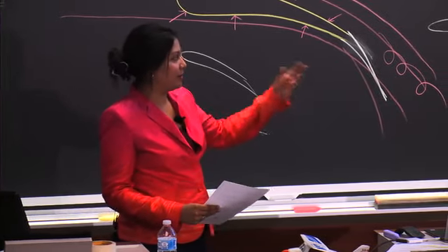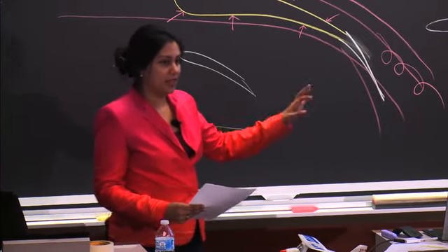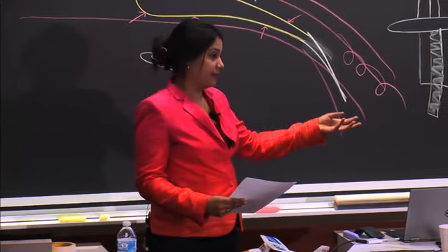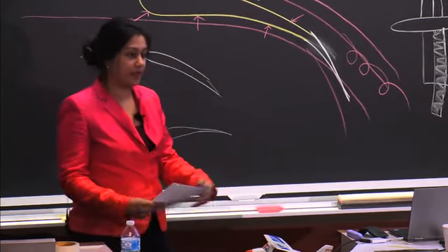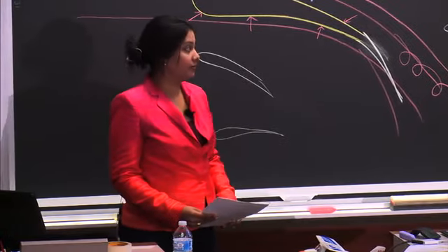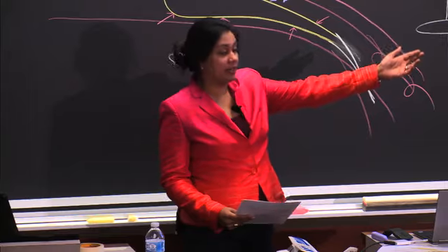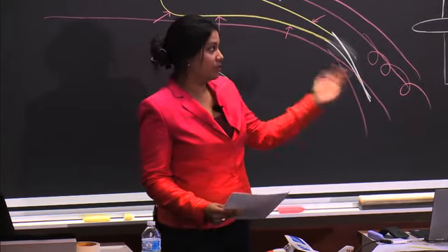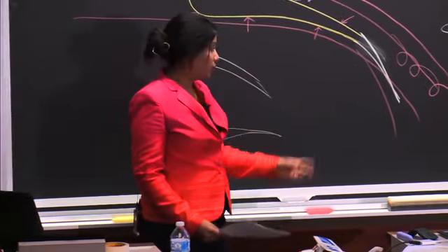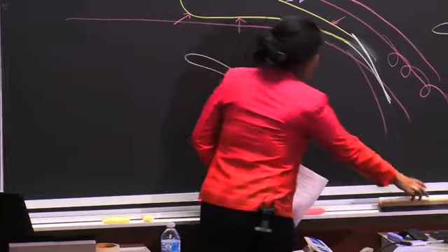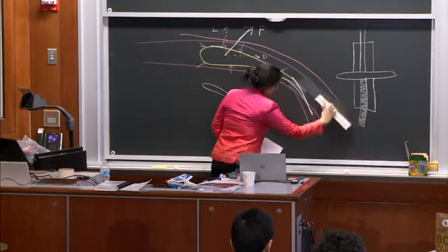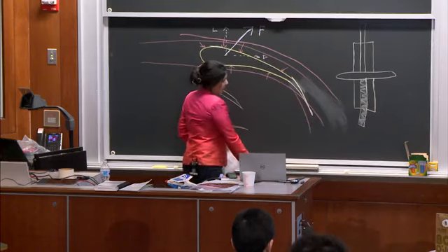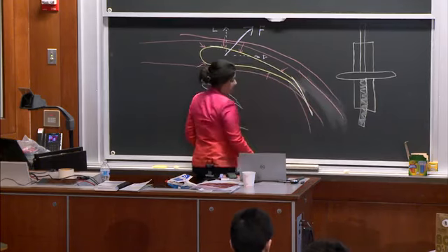And we impose some limitations or conditions on the airflow, which are not actually true, but help us with approximating lift. One of those is the Kutta condition that you see at the bottom left, which is this smooth flow off. Basically you say that none of this turbulence is happening, and the air moves very cleanly off.